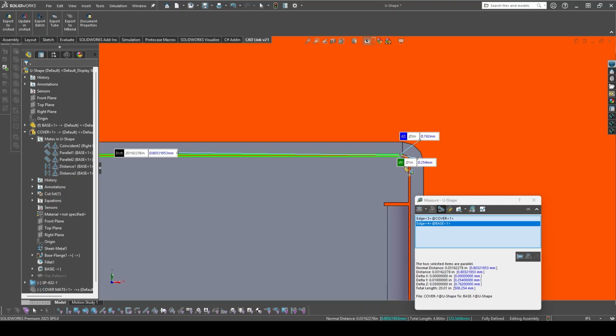for the part. The first step before beginning your design is to analyze the requirements of your design to determine which aspects and features are going to be critical to the fit, form, and function of your final product. Now, it is important to not over-tolerance features that are not critical to the function and allow our engineering and design services team to make any required changes to your design to meet our manufacturing tolerances.